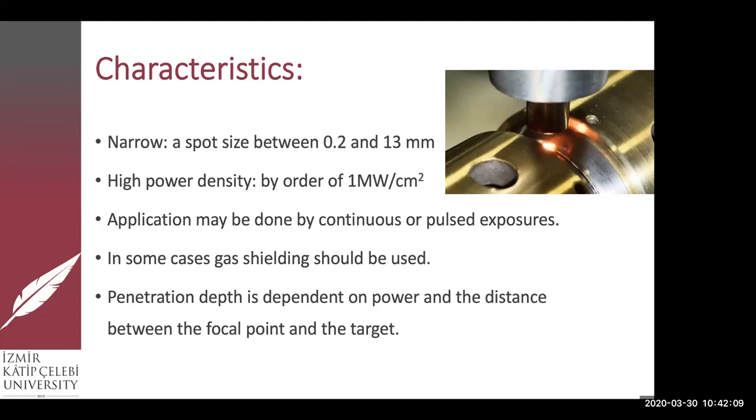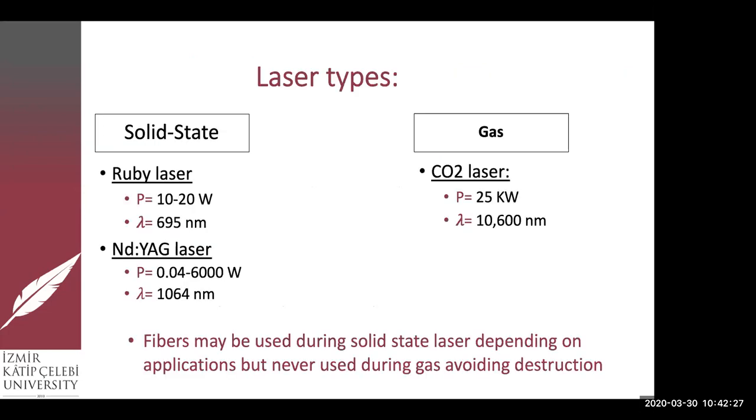Penetration depth is also dependent on the power that is used, and on the distance between the focal point and the target. So the closer the distance, or the smaller the distance, the higher the penetration depth is. What are the laser types that we can use?